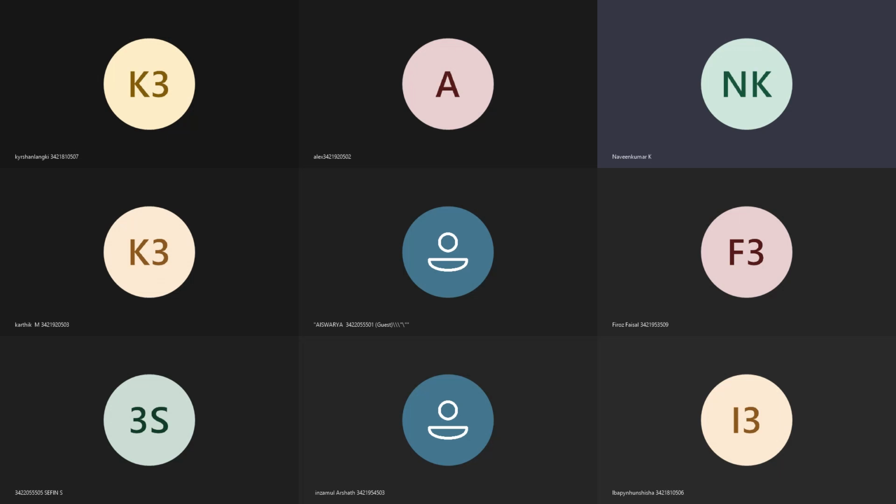But if you want to design the bridges, you have to follow the IRC loading condition. In the first case, you followed a specific code book, Indian Standards 875 part 1 to 5. But for the bridges, you will follow the IRC loading condition. Then for the analysis purpose, you follow the influence line method.